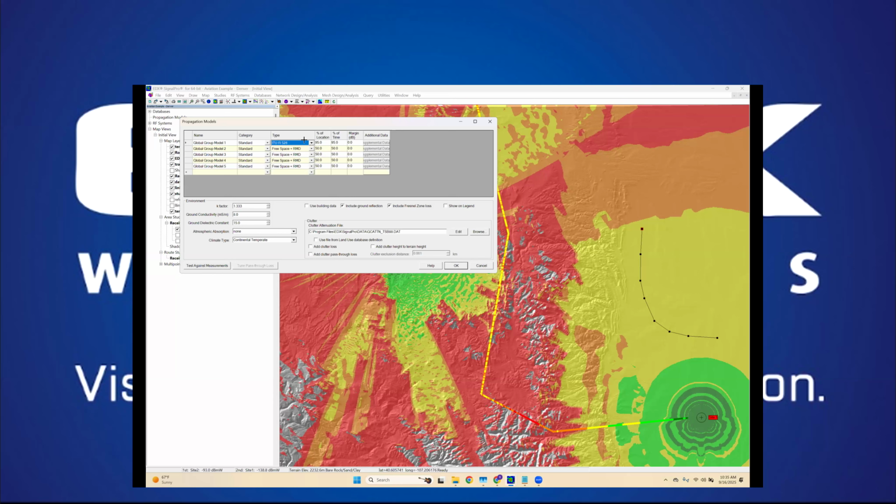Scintillation is the one that's included in the 528. So in other words, upper atmospheric effects and the decorrelation effects that take place in the upper atmosphere are handled by this ITUR 528. And so if your aviation need stops being near the ground and turns into we're going straight up and then going east really fast, really this ITUR 528 is the more appropriate model to choose.